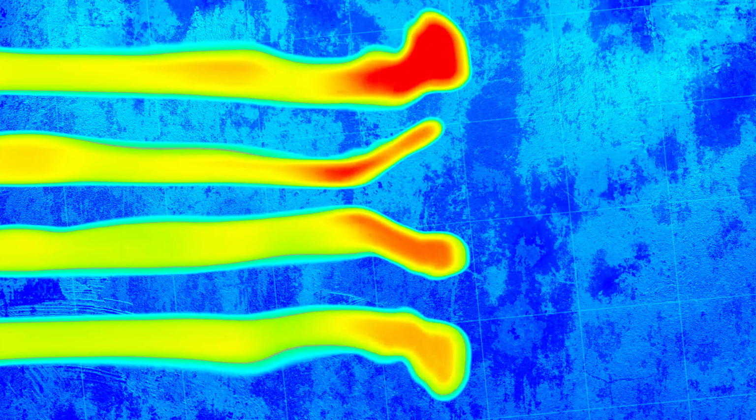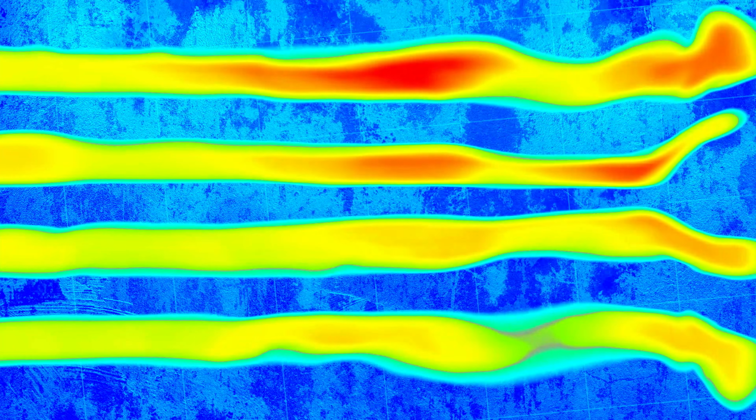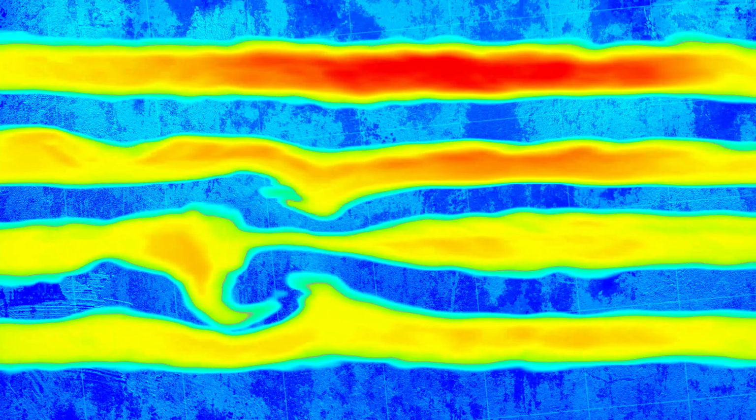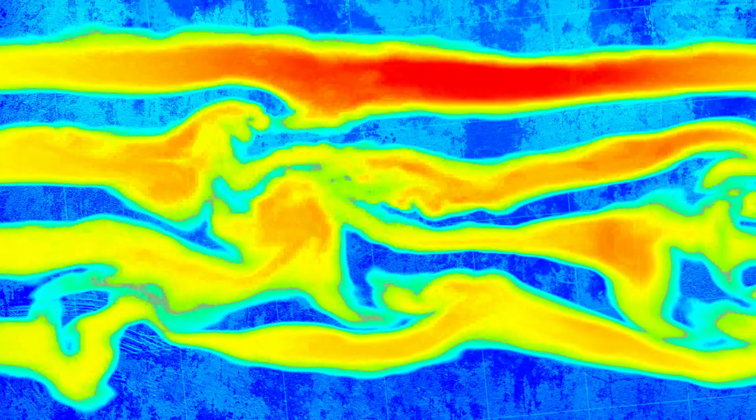Here we have an example of the laminar flow regime. It's characterized by smooth, even flow. The fluid is moving horizontally in layers, and there is a minimal amount of mixing between layers. As we increase the flow velocity, we begin to see some bursts of random motion. This is the start of the transition between the laminar and turbulent regimes. If we continue increasing the velocity, we end up with fully turbulent flow.